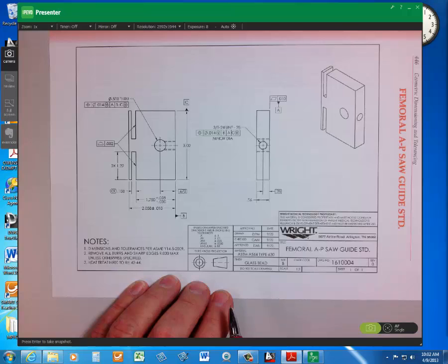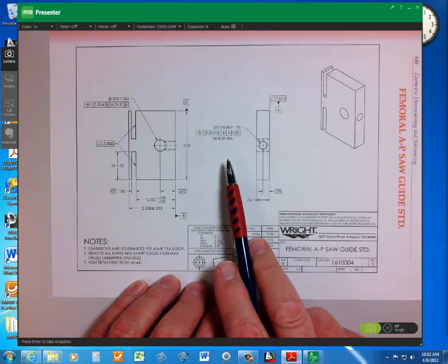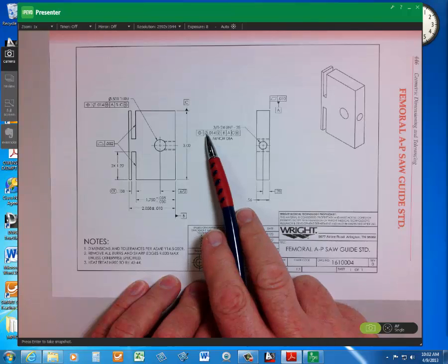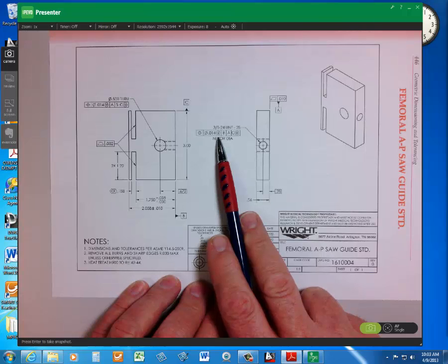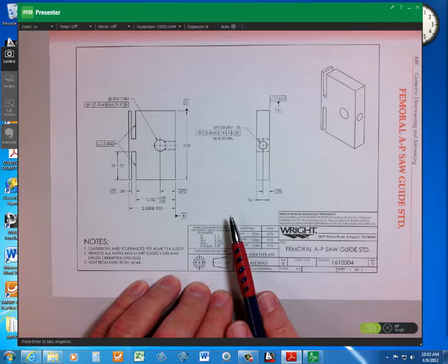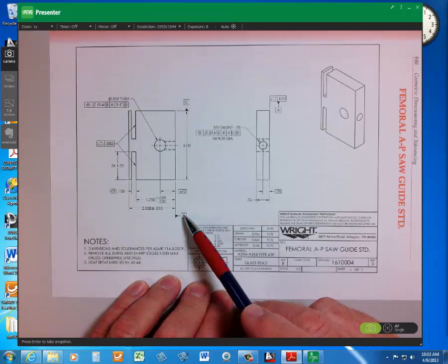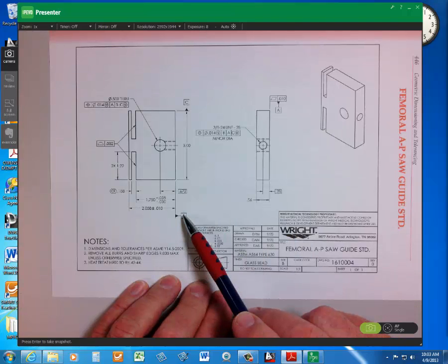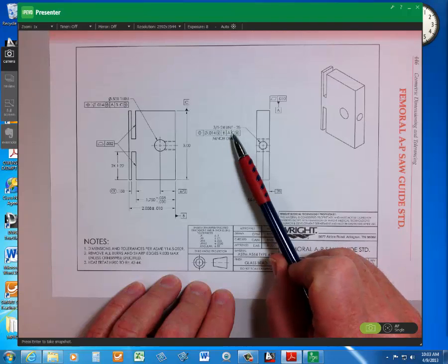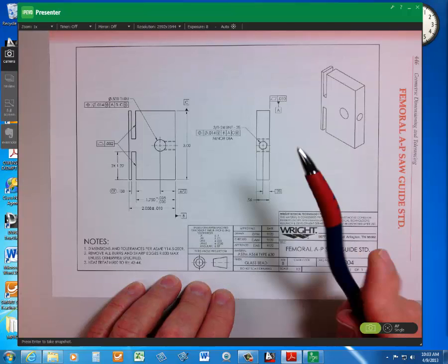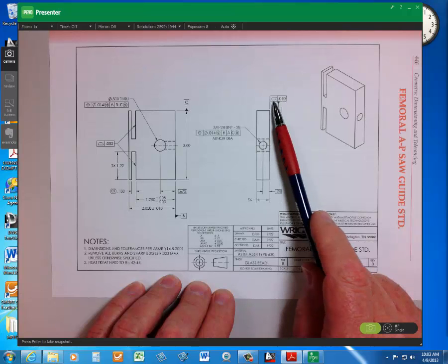Meaning of the information, this feature is controlled by a cylindrical position tolerance of 14 thousandths at max material condition, relative to datum B first. Okay, so where's B? B is here. Usually your first datum is the one the hole is perpendicular to, so that's usually what we list first. And then A in this case is listed second, order of precedence. It's the back of the part, and it has its own flatness control.